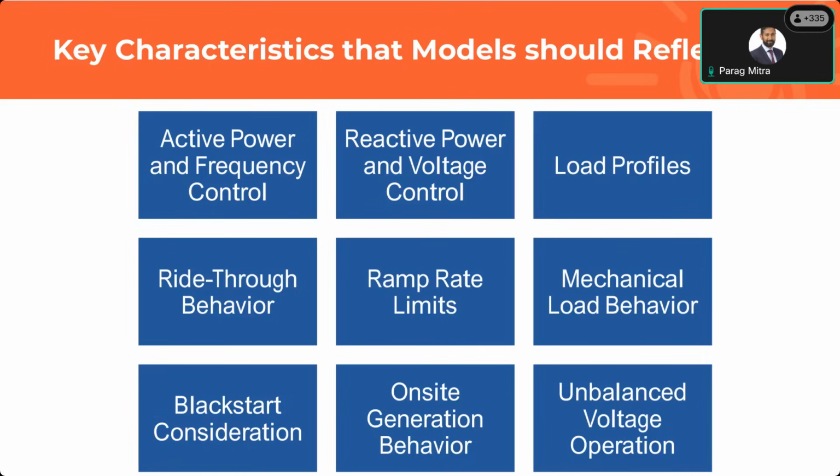It should be able to model the ramp rate limitations. It should be able to model the mechanical load behavior. So it's not just modeling the power electronic device that is the front end of any kind of load facility, but what happens at the back end also has a material impact on how the device operates. A simple example is if you're running a motor through a variable speed drive, the load dynamics of the motor can also have some impact on what happens to the system. So you should be able to model those things as well.